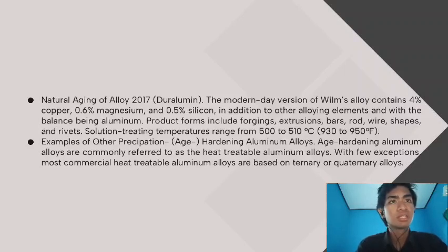Solution treating temperatures range from 500 to 510 degrees Celsius. During solution treatment, the temperature should be maintained within plus or minus 6 degrees Celsius of the required treatment temperature.